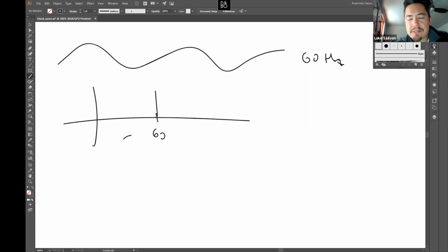I mentioned 60 hertz because in the US, that's the frequency of the current in the walls. So you commonly get 60 hertz noise in electrical recordings. In the ephys lecture, we're going to talk all about that, and grounding, and getting rid of 60 hertz noise. It's kind of 50% science and 50% voodoo. But one of the things that happens in practice is that a lot of times you get a distorted 60 hertz wave that's not perfectly sinusoidal. Maybe the simplest example would be a square wave at 60 hertz.